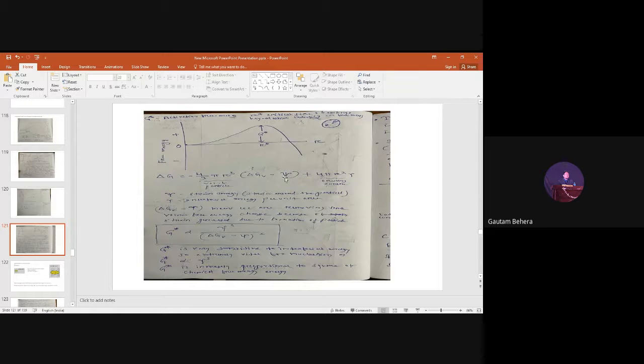This was missing, yes, only this term was there. This term is there because of strain energy. You have to remember, strain around the particle. Here a precipitate is a solid particle and it is forming in a matrix, so it is creating a strain field around the lattice of the matrix. That's why an additional term has to be deducted from this part.